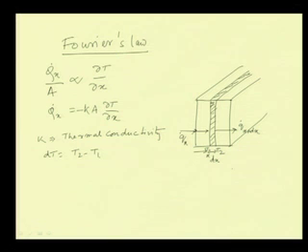The difference in temperature is always final minus initial, but if heat is to be transported along the positive x direction, then T 1 has to be greater than T 2. This is by the second law of thermodynamics: heat cannot be transported from a lower temperature to a higher temperature. So, heat has to be transported from higher temperature to lower temperature, and under that situation